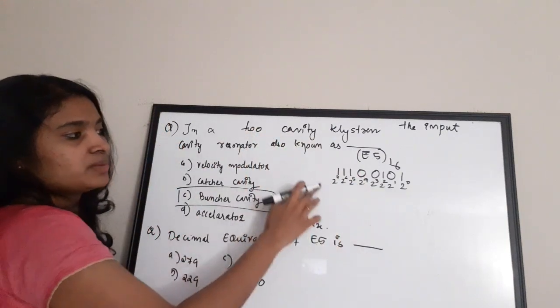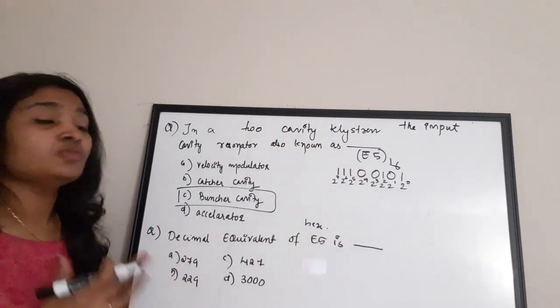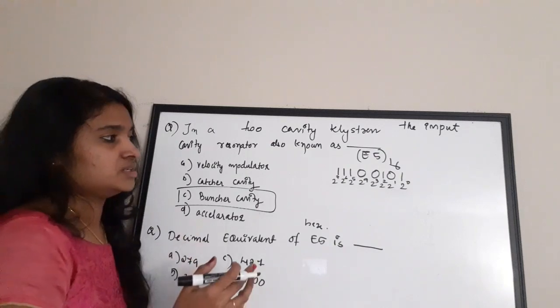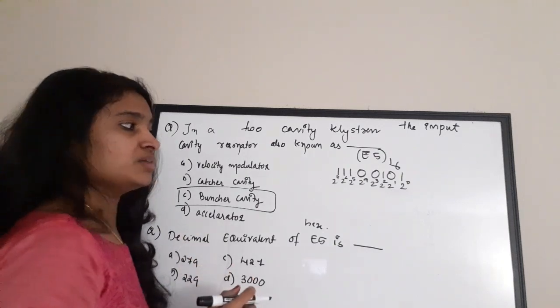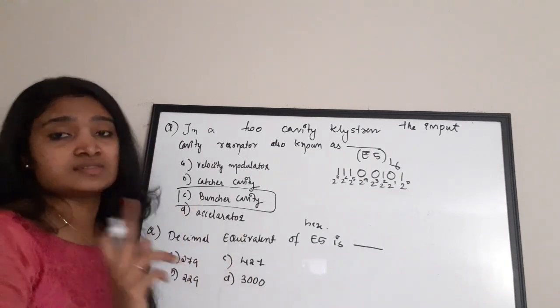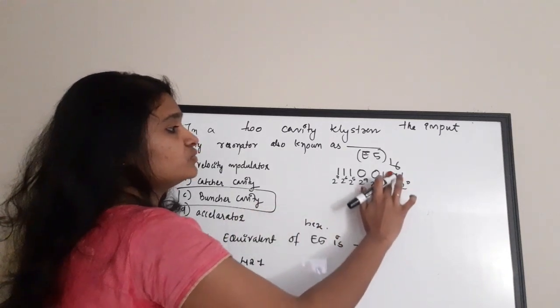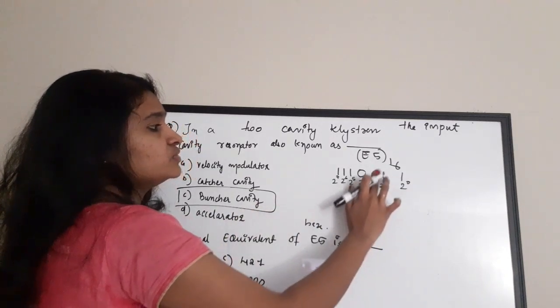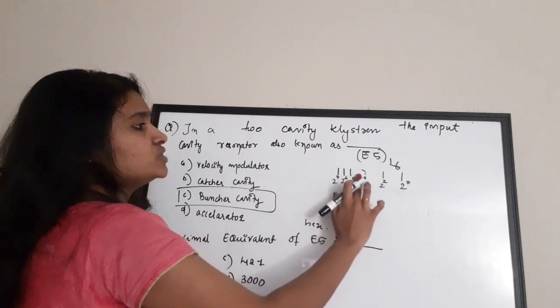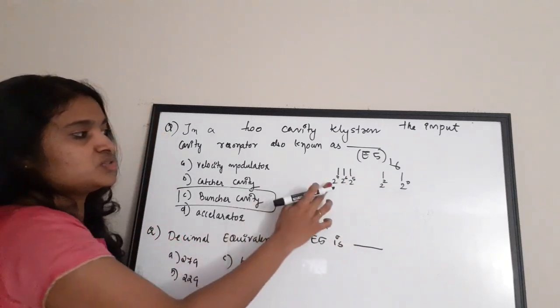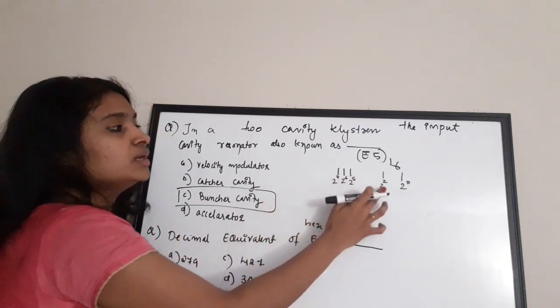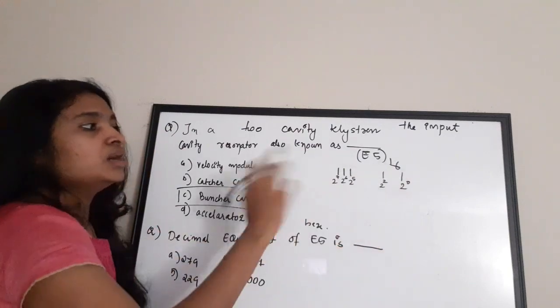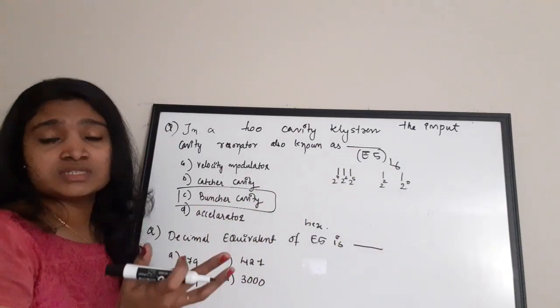That is, below each number I have written the weights in binary representation. Now I can cancel off the numbers above which there is a 0. So I'll remove this, this, and this also. Now there is 2 raised to 7, 2 raised to 6, 2 raised to 5, 2 raised to 2 and 2 raised to 0. I've removed all the numbers above which there was 0.